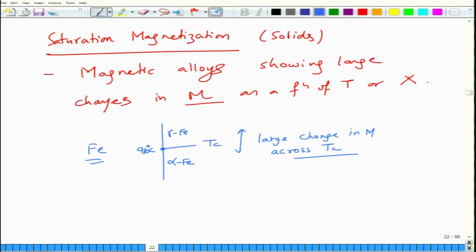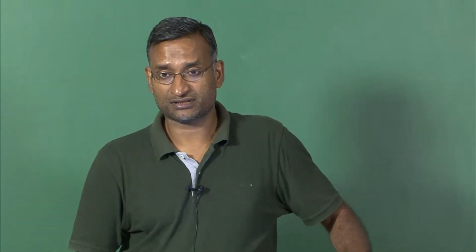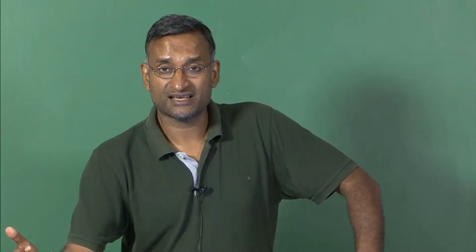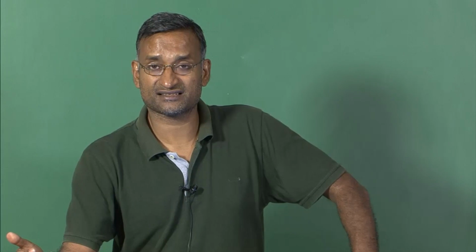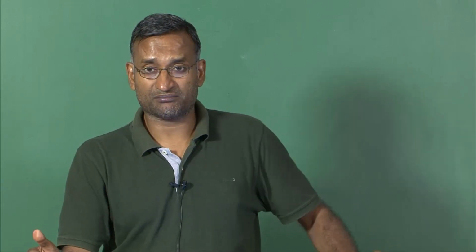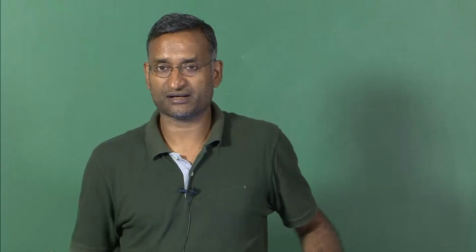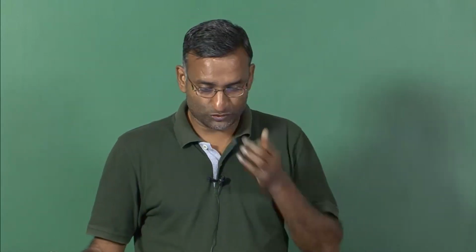So essentially what we have done in this lecture is we have looked at various methods that are used to determine the phase diagrams of simple metals and alloys. The techniques that we follow are thermal analysis, which means measuring the cooling curves as time versus temperature plots for pure metals as well as for alloys, and then mapping out liquidus and solidus temperatures to construct the phase diagram. And this can be done for both isomorphous and eutectic systems. Measurement of solvus is a lot more difficult in the solid state. As a result, you complement various techniques, microscopic techniques, X-ray diffraction, temperature dependent X-ray diffraction, as well as resistivity, dilatometry or magnetization techniques to complement the information and make a phase diagram with accurate data. And measurement of composition is very critical in these things. It should be accurate. So this is what we have done in the past few lectures.